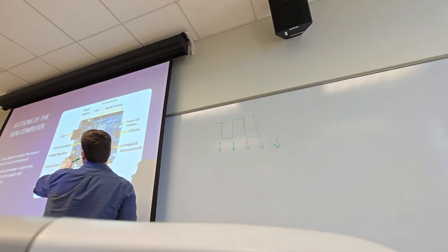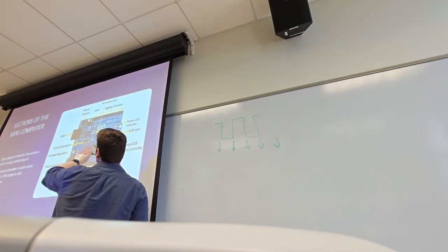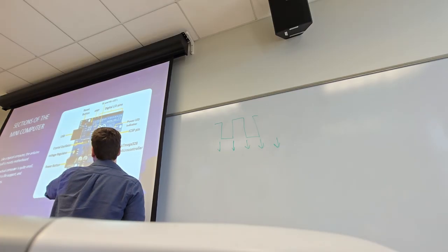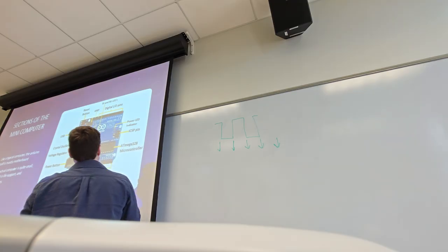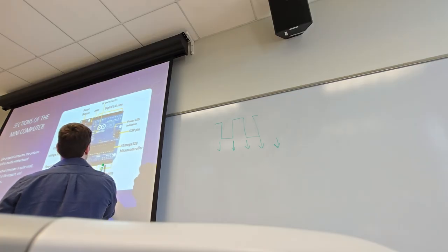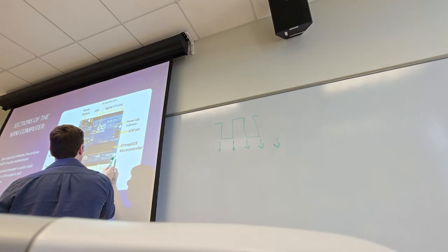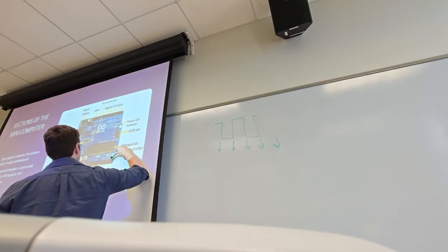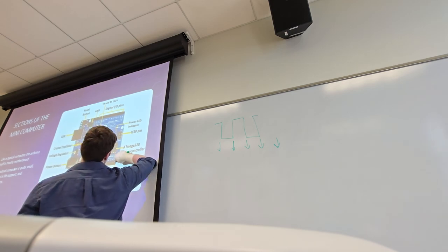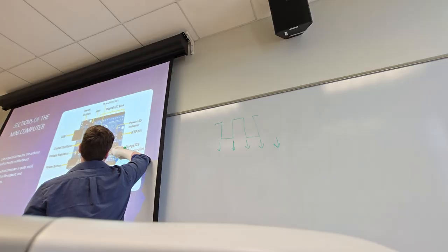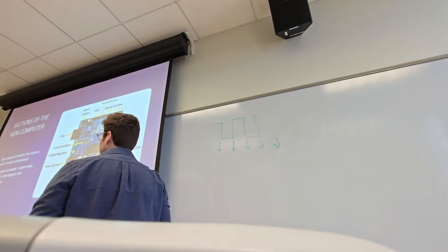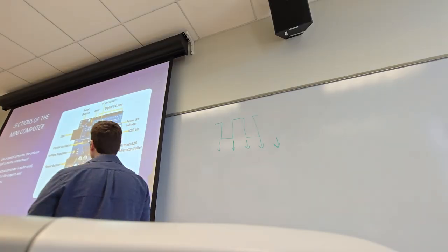It's things to power it, to keep it alive, to filter that power, to talk to the board through USB, right? That's kind of all the rest of this does, as well as to physically connect each of these silver pins, okay, to one of these. These are called headers, okay? When you can put a pin into it, it's called a female header, and when it sticks out, it's a male header, okay? And you can actually see, if you look real close, because this JPEG is really artifacty, that each of these lines go straight into each of these pins, and that's literally what we're doing. So each of these pins we're making a physical connection to, and we wire in a breadboard wire, okay?